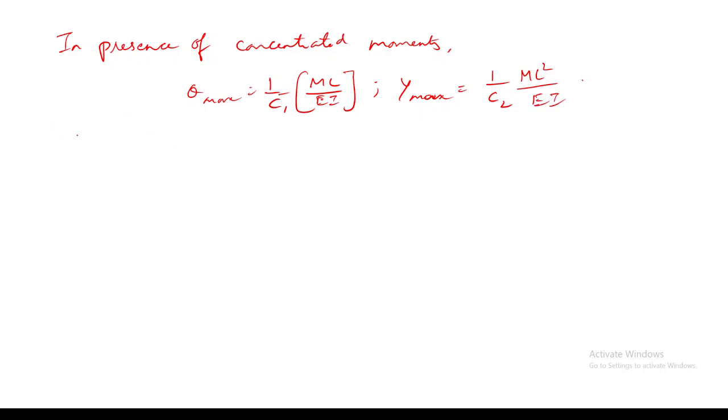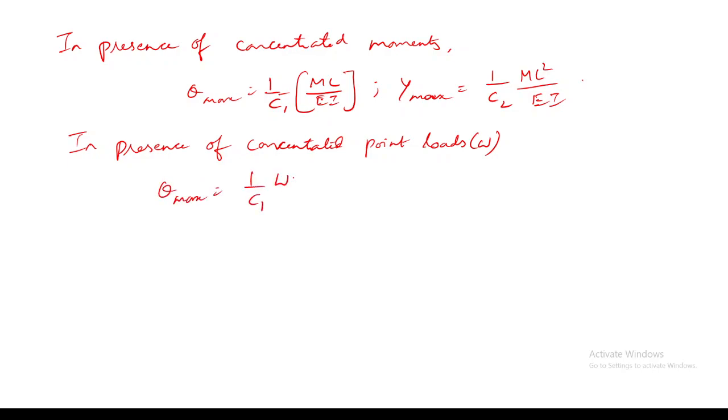Similarly, in presence of concentrated point loads W, which you can cross check with your formula sheet also, theta max is 1 by C1 times W L square divided by EI, and y max will be 1 by C2 times W L cube divided by EI.